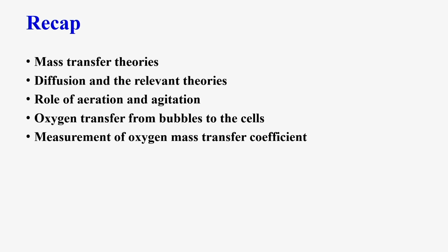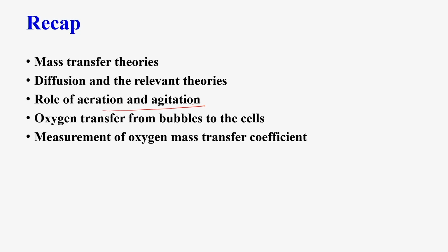Initially we discussed mass transfer theory, particularly Fick's law of diffusion and two film theory. Then we discussed the role of mass transfer, particularly in aeration and agitation. We discussed aeration separately and agitation separately. In aeration, we discussed that the mass transfer resistance lies in the liquid film, and how to calculate this film mass transfer coefficient KLA using experimental methods and also different correlations, followed by agitation and mixing,